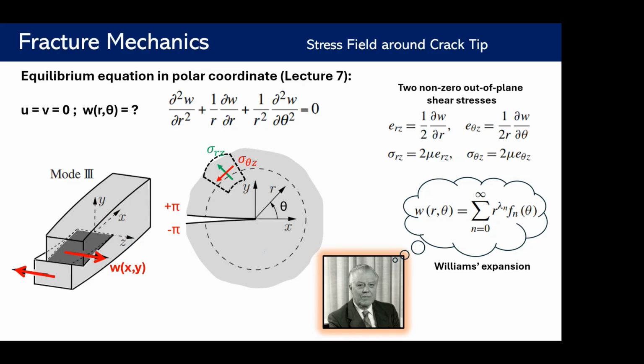What's the value of r? R is here defined as the distance to the crack tip. So you can assume that we have a polar coordinate system whose origin is located exactly at the crack tip. Is it the same as the length of the crack? No. This problem is solved for a general fracture.